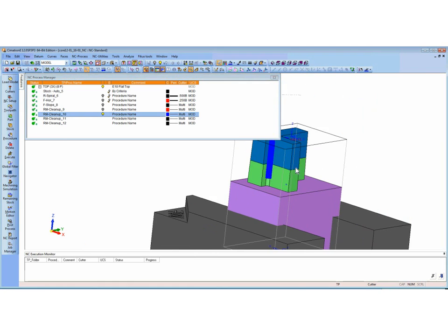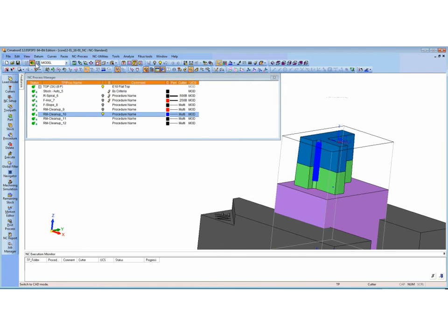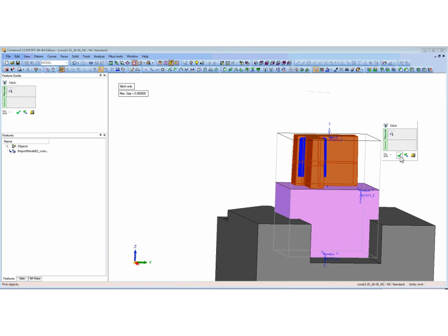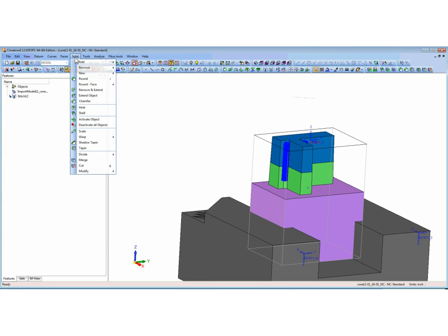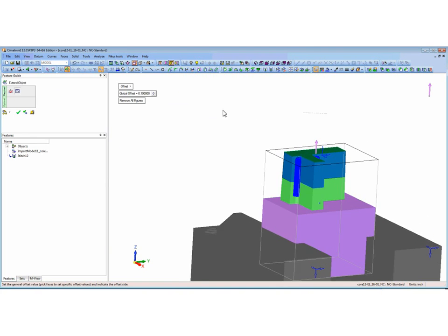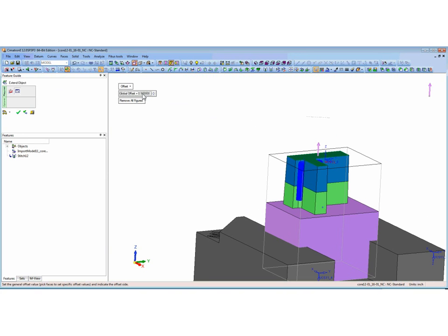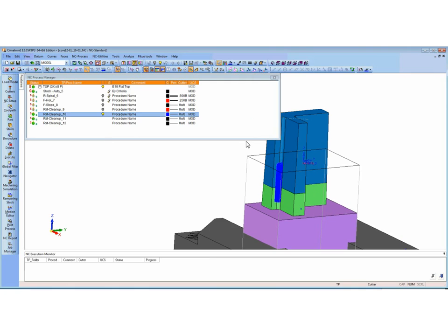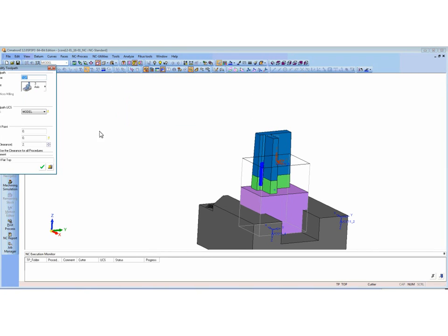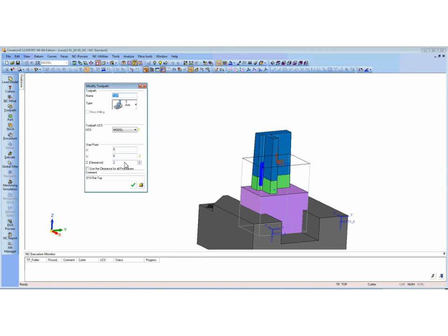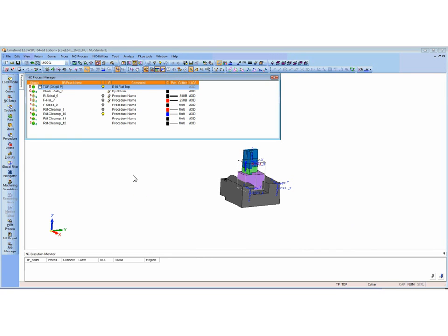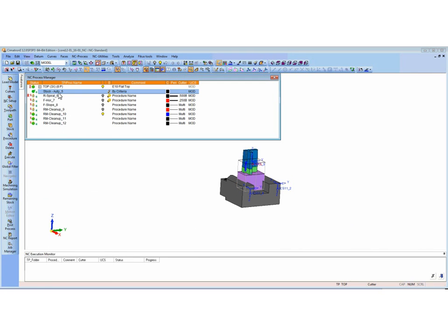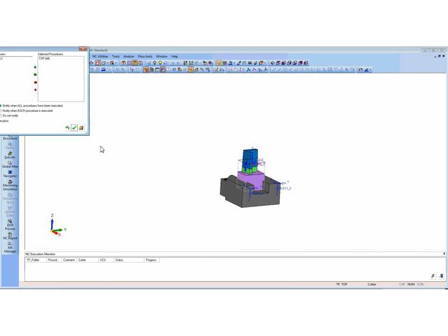Okay, so let's do a couple things. I'm going to switch over to the CAD side, and we're going to stitch this just like we did earlier. And I'm going to do an extend. We're going to push this wall up, say a 1/2 inch. Okay, and then we're going to go back and recalculate this. Execute.